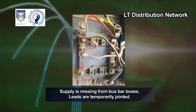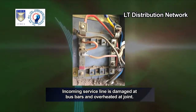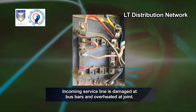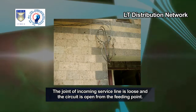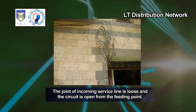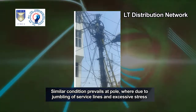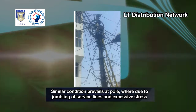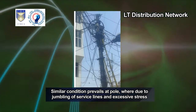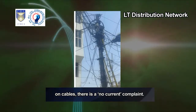Leads are temporarily jointed. Incoming service line is damaged at bus bars and overheated at joint. The joint of incoming service line is loose and the circuit is open from the feeding point. Similar condition prevails at pole, where, due to jumbling of service lines and excessive stress on cables, there is a no current complaint.